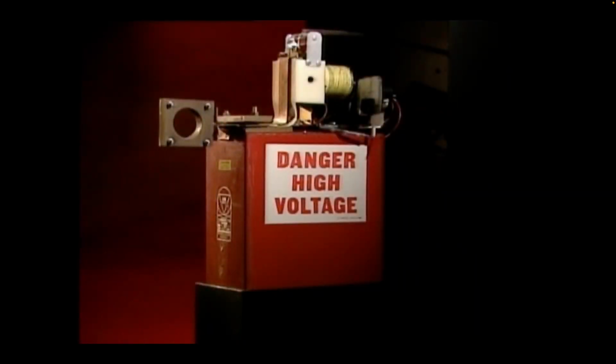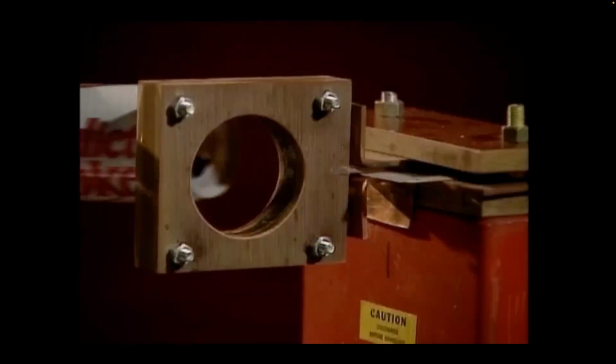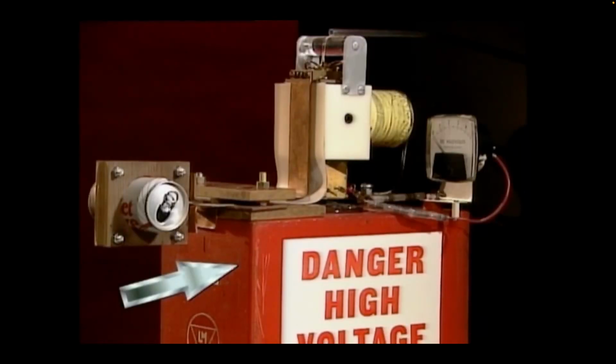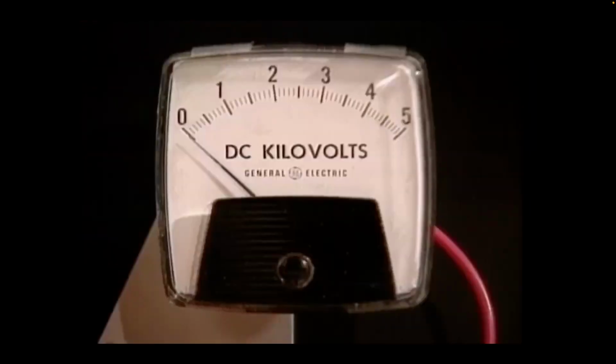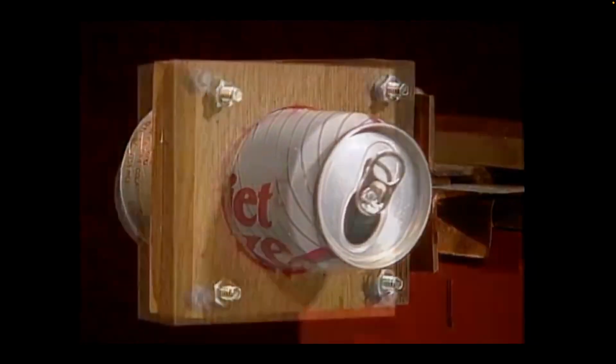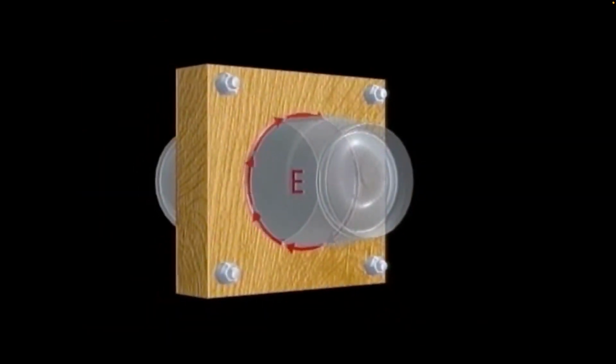This specifically demonstration uses electromagnetic field to break a cola can into two pieces. An empty aluminum cola can is inserted into this 3-turn coil. This 400 microfarad capacitor will be charged to 3,000 volts as read by this meter, and then will be discharged through the coil. Let's charge the capacitor. When the capacitor is discharged, it creates an electron current in the coil, which increases rapidly to a large value.